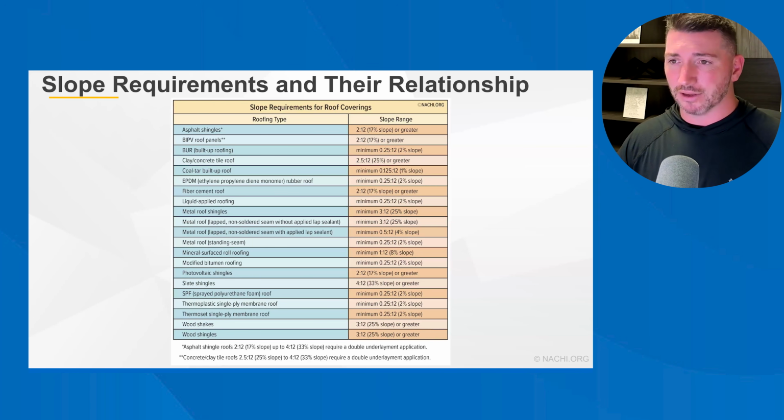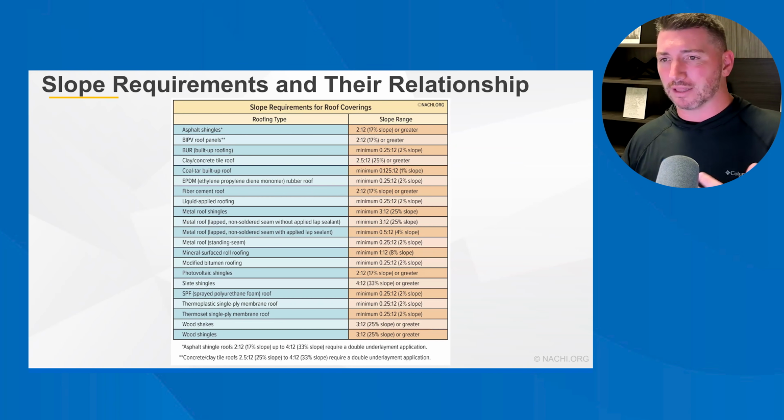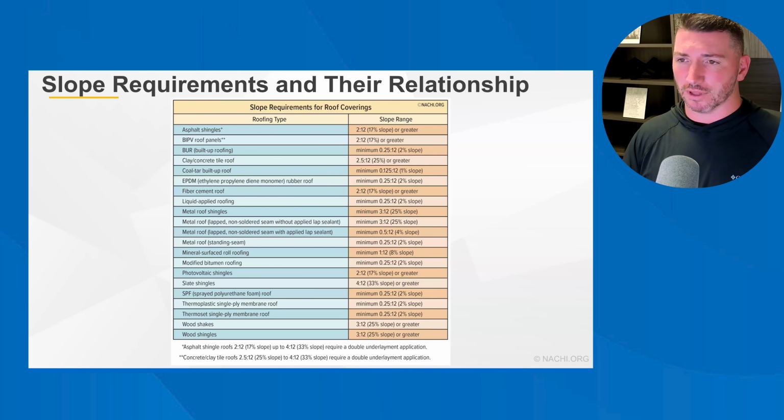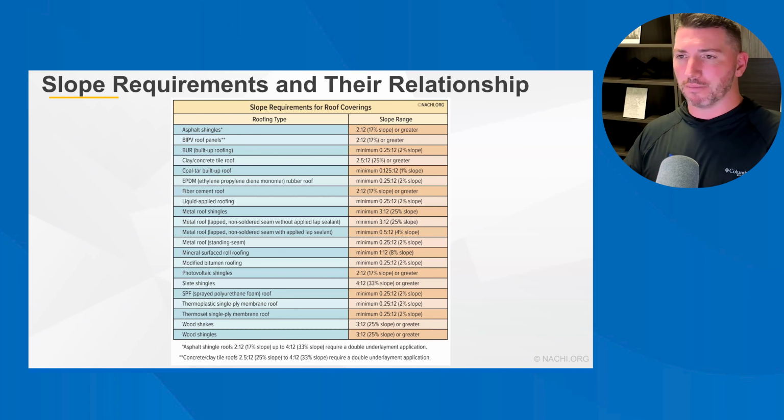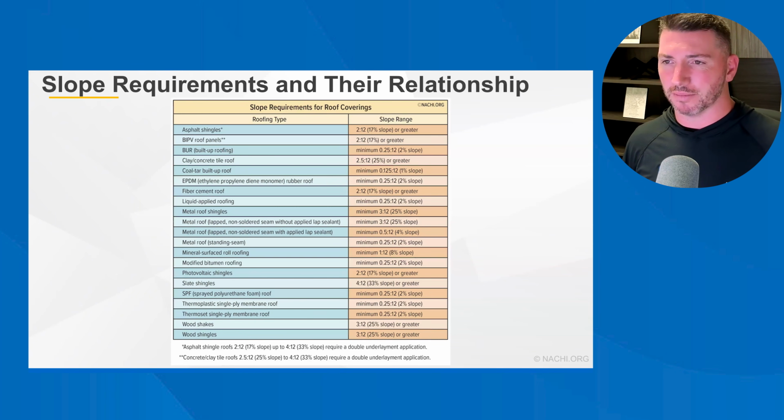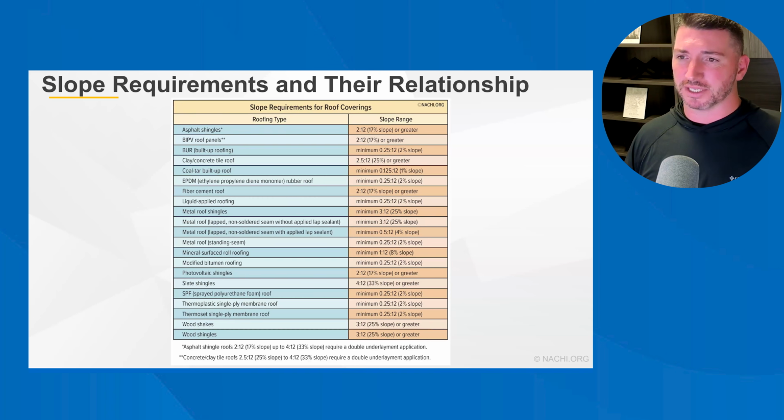Asphalt shingles and any other tiles. Again, think about the way that the material is installed. If you've got an impermeable membrane, it's fine if water sits there a little bit longer. But anything where there's a tile or a shingle or something modular where there's a bunch of fasteners installed and then lapped over, well, if you let water sit there, it's going to back up to where it gets to the fasteners and penetrates into the inside of the building envelope. So that's a problem. So anything where it's modular, you're putting pieces on and nailing them in and then lapping them on top of each other, that's not a waterproof system. That's not impermeable. It's a water resistant system that's designed to divert the water off the top of the roof.